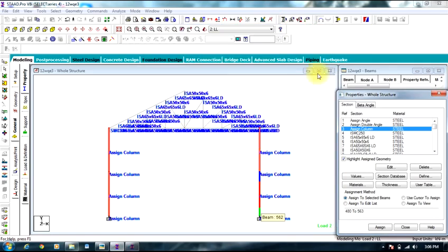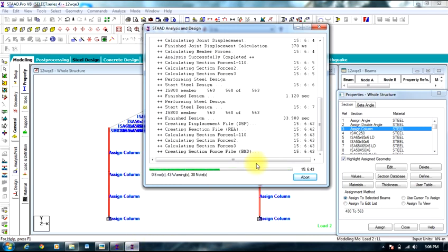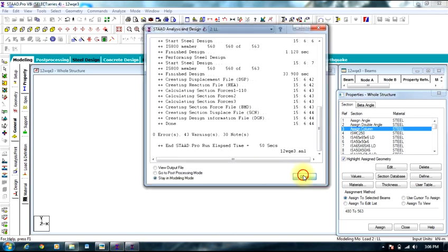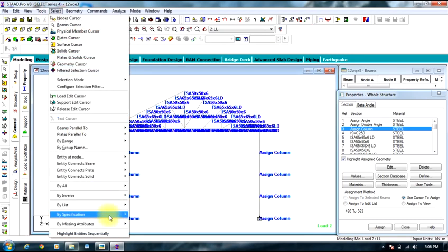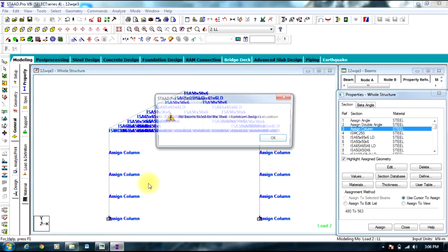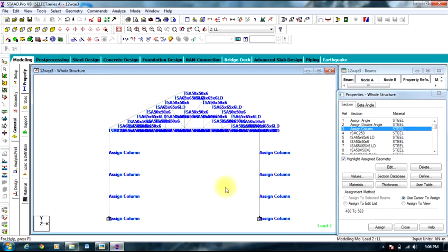If we use select command in design tab and there still exists any failed beams, then we must change the member. If suppose angle fails, then we can select double angle or we can select a channel. We need to improvise with time in these situations. So you can see there are no failed beams.